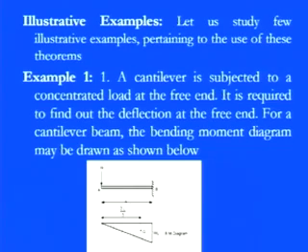So you see here, because we have already discussed this cantilever beam, at the free end we have this point load, or concentrated load, and we calculated with the use of the direct integration method. But here we need to calculate the deflection with the use of the area moment method. So for that, again, as I told you, all the focus is on the bending moment diagram, because it is a semi-graphical method. So first we need to calculate the bending moment diagram.